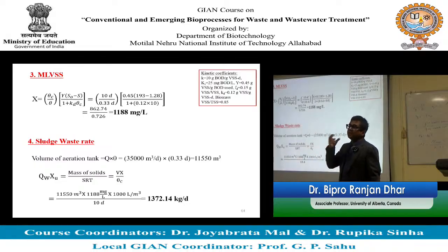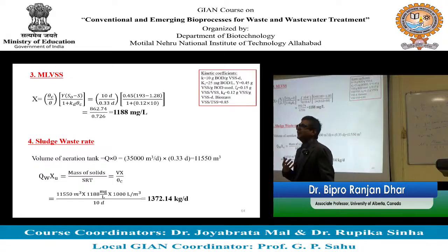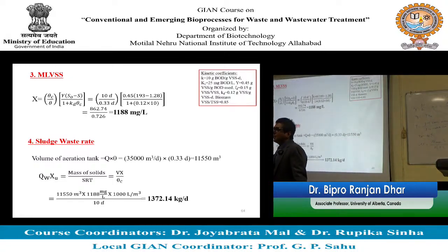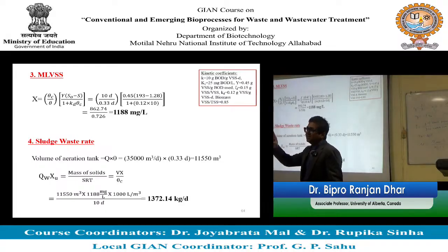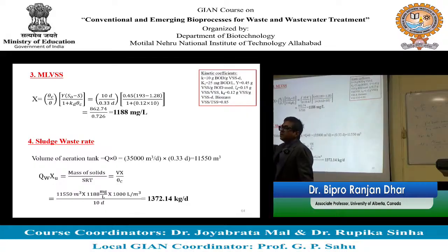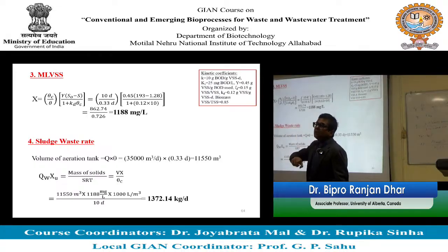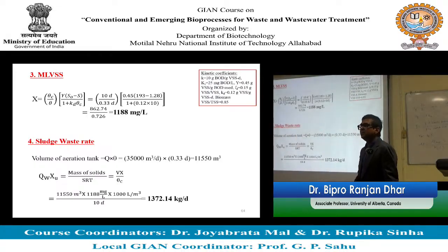So that's the calibration of those models. Software feels very handy, you provide some input and get some output. But one of the key challenges of using software in this field is calibration. You have to do a lot of sampling, a lot of fractionation, and initially do some modeling and compare it with field data. Then you validate the model, and then you use it for any further optimization.